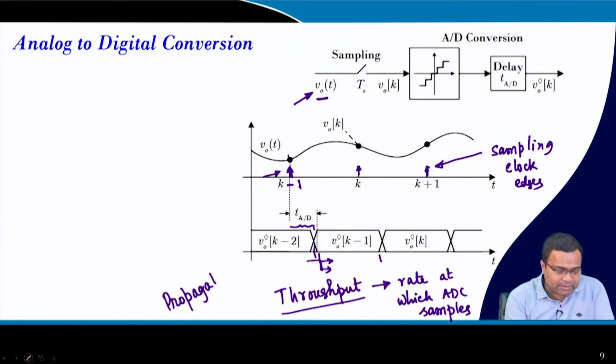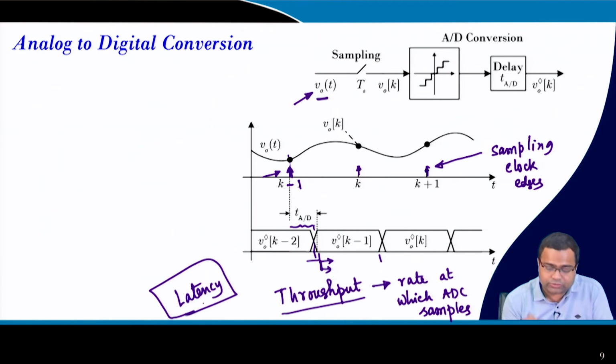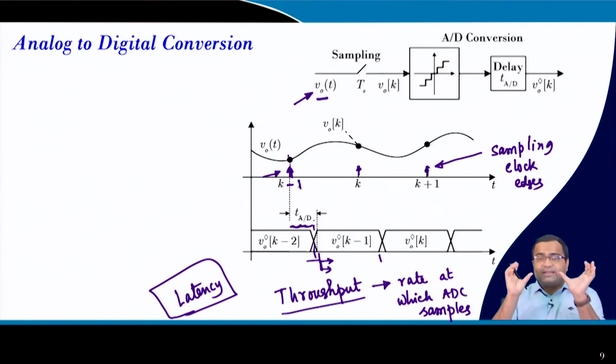Sometimes in ADC terminology it is called latency. So, you call it latency, and for us this is one of the most important. This latency will decide what my delay is. If we take a pipeline ADC, the delay is generally decided by the number of pipeline stages. So, if there are 6 pipeline stages, your delay will be 6 times the sampling